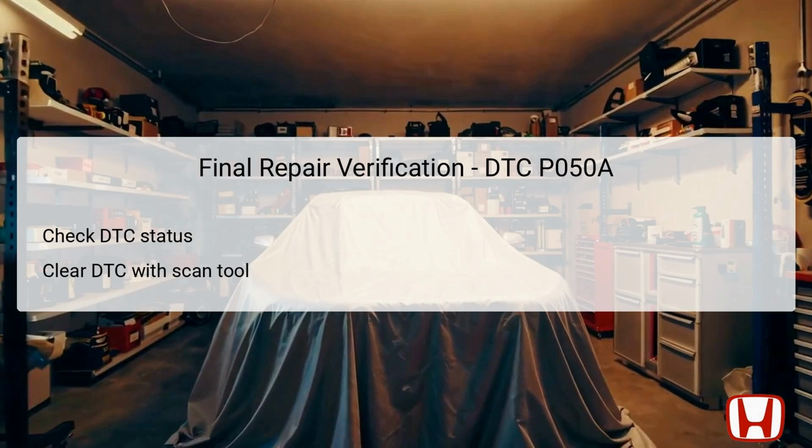Furthermore, it is advisable to clear the DTC using a scan tool, allowing the PCM to reset and reevaluate the system under normal operating conditions. Confirming the absence of the DTC after several driving cycles will ensure that the repair was successful and that the cold start idle air control system functions as intended.